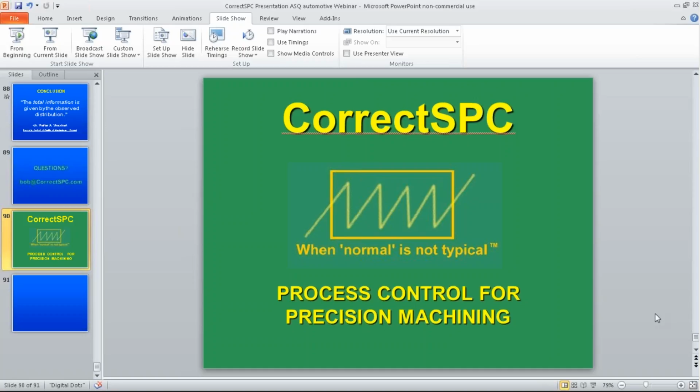Since the measurements are dependent, have you looked at EWMA control charts? Yes, but it is still not as powerful as this one because of the ability to control all diameters with this one. And this is actually far simpler than the EWMA. But yeah, that's one of the examples we use. And again, it has a sampling issue that this doesn't have. Then another comment: for clarity, measurements should read data. Well, you're measuring, but you're collecting the data on the measurements.